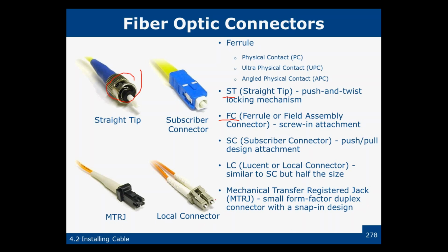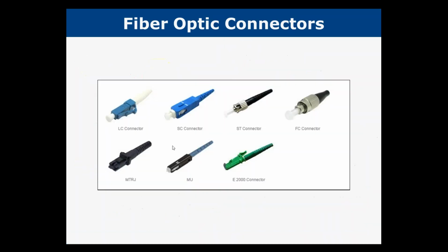The connectors have changed. One thing you want to be sure of: these connectors all come with covers. When they're not in a receptacle, you want to be sure the cover's on, because if the tips get dirty, it's going to affect your transfer, and they do need to be cleaned occasionally. This is a picture that I found. This is the FC connector, the ferrule connector. I said it's kind of like a version of this but bigger, and it is. Different connectors.